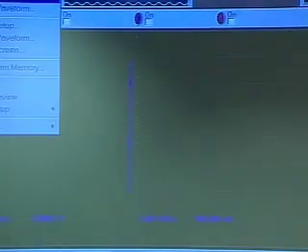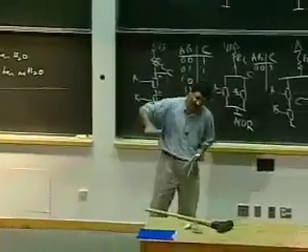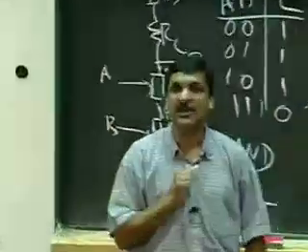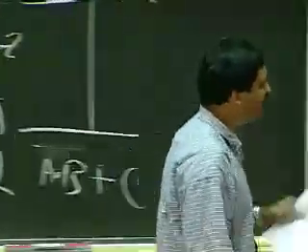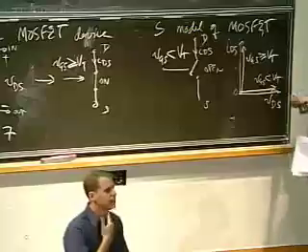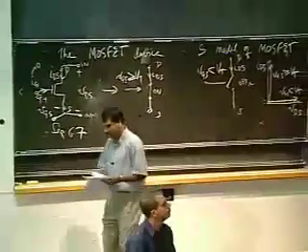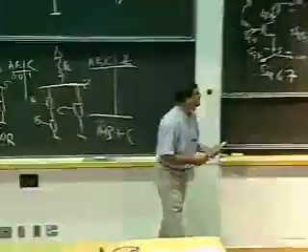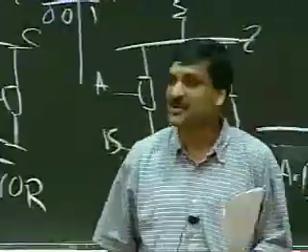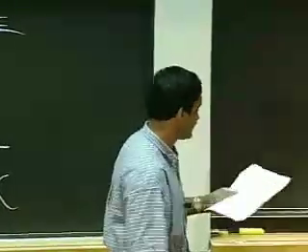Okay, I really like to think of this pressure analogy if I get confused. Whenever I look at a MOS transistor and I need to look at VGS and so on, I always think, when VGS is greater than VT, lots of pressure on a switch, it turns on. Just remember that, and then you won't forget this VGS thing. So that's the behavior of a switch, and so voila, there's our switch. Okay, so I've given you a 3-terminal element that is a switch that is controlled like a mechanical switch.